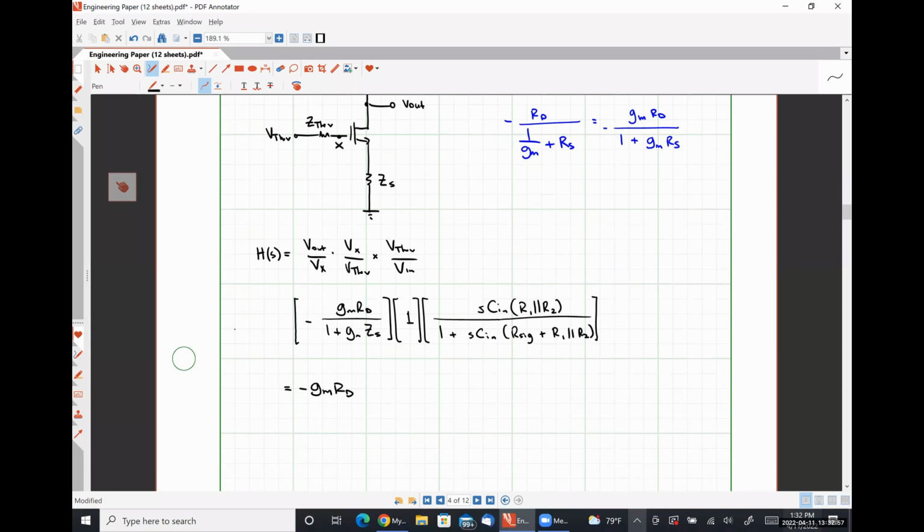It has to. Just looking at it mathematically, as S gets really large, that fraction is going to approach 1, which should equal just our regular gain. Let's get into that specifically. You're thinking about it correctly. But we're going to break it down into a very specific form that tells us where our poles and where our zeros are, so that we could draw a Bode plot of how this guy behaves, and it will literally exactly match what we simulated the other day.